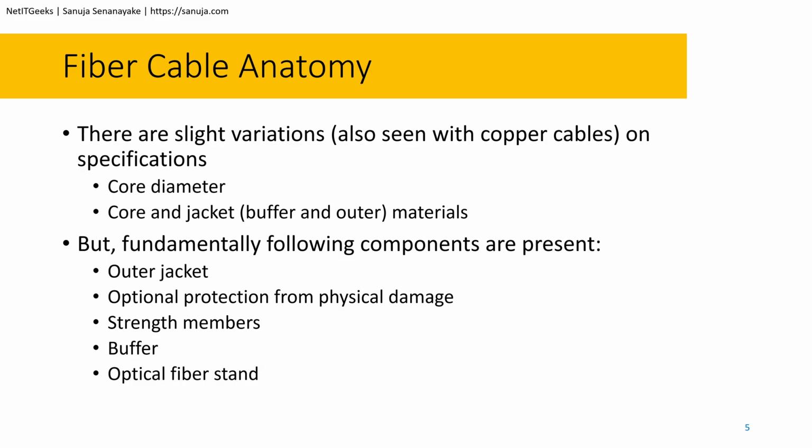And those are basically a little bit flexible fiber optic cables. But if you're installing outside, for example, let's say you're doing direct burial cables, obviously they're going to have specific jackets specifically designed to have that metal or Teflon cladding, for example, allowing you to install the fiber cables in a directly buried situation.